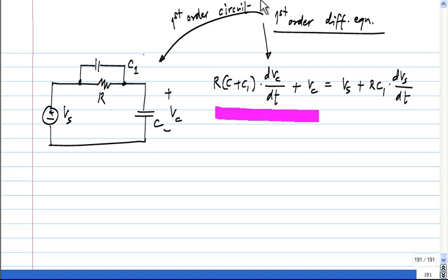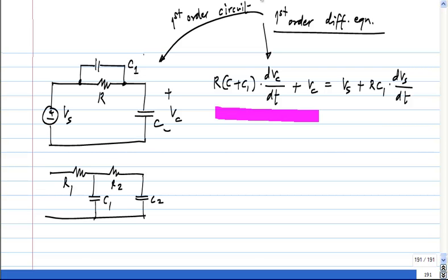Should I expect a first order relationship here? Okay, let me take some other circuit which you can try out writing the differential equation for, and let's say it's also driven by Vs. You can pick any variable and you can try this out later, but you will find that the equation you get will be second order, because of the presence of two capacitors. So what is it that makes the earlier circuit first order?